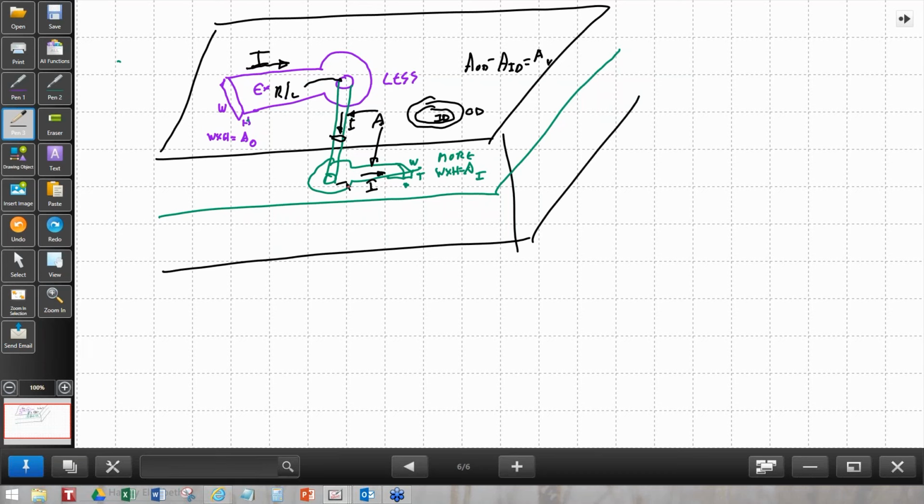If your board is very, very thick, it may even be worse than that because the via doesn't have much surface area to dissipate heat. If you have a board that has a plane layer, that's an entirely different thing, because you may be using the plane layer to dissipate heat.